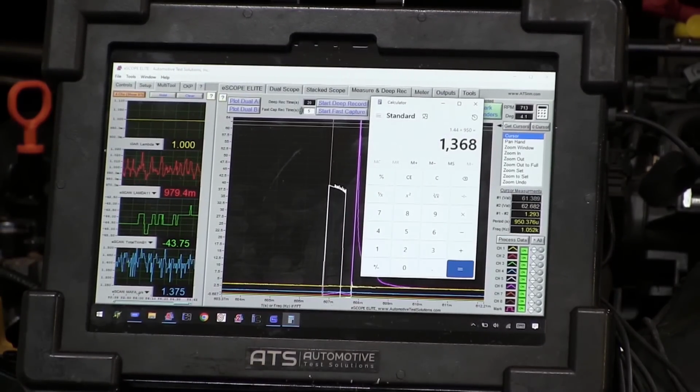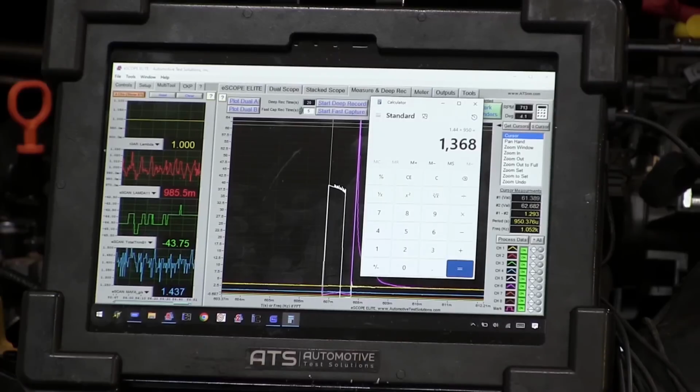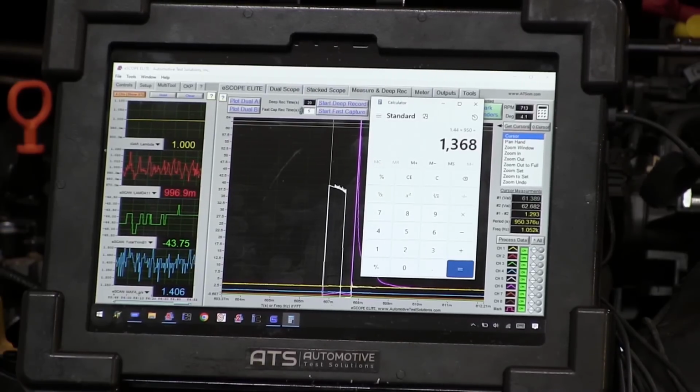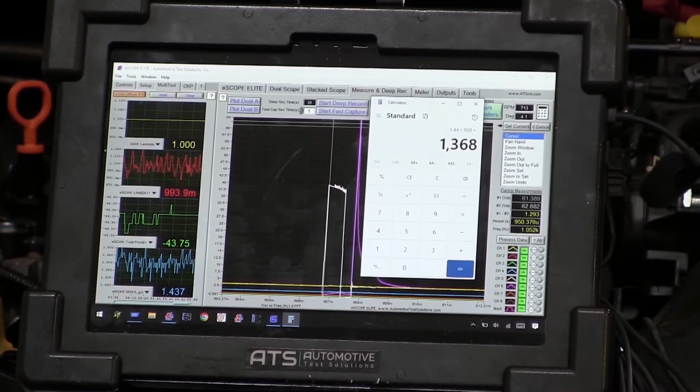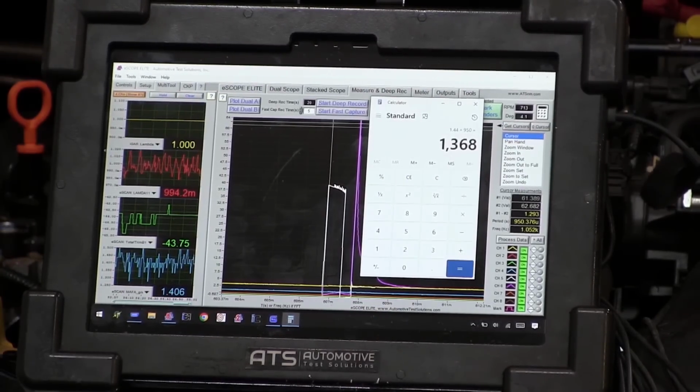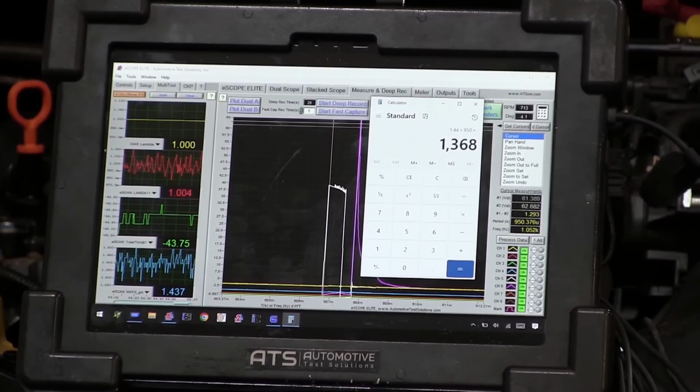So what I've got to do now is get another scan tool, and I don't know much about Honda. I don't know if they have alcohol calculations in these cars. But guys, I've been burned on this problem on a Ford, because Ford calculates alcohol content, and if the alcohol content it calculates is too high, it'll have to trim the fuel to fix it. I just don't know enough about these Hondas, guys.